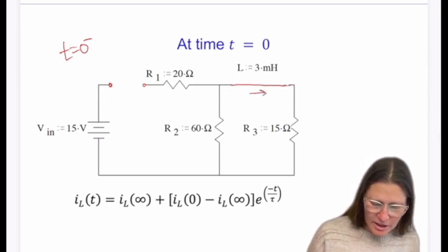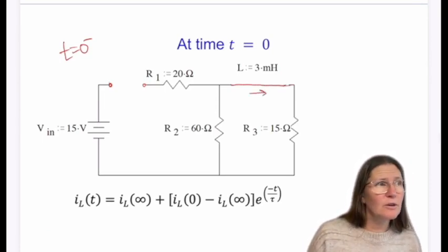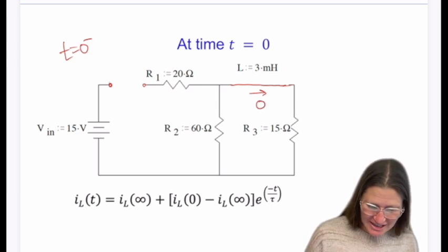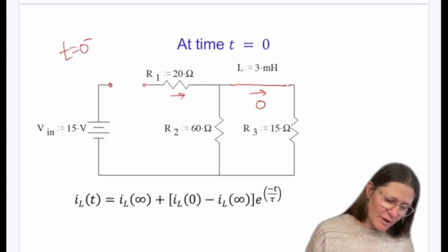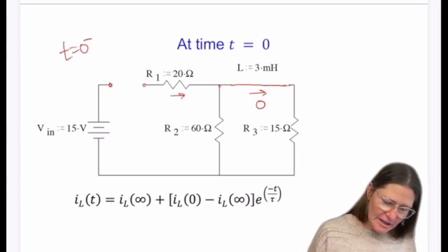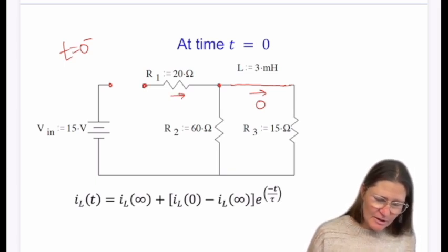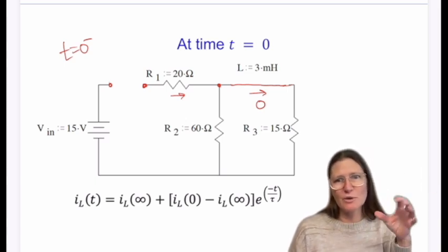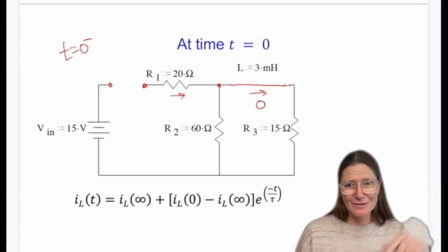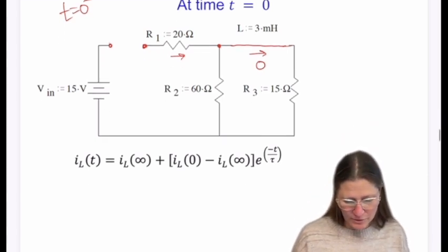And finding the current here, would you guys find the current? Thank you, 0, correct. No current flow. And then this also will be floating because this one is floating. So there's no pathway back from one side of the plus 15 all the way back to it again. So without a closed path, no current flows in there.